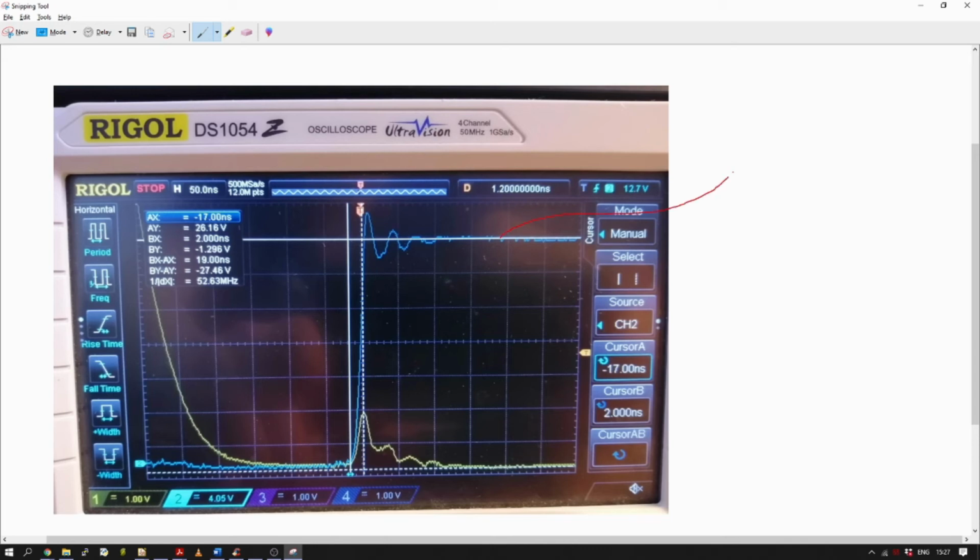So this here is the drain of the low side MOSFET, and as you can see, we're around 0 volts. Then there's a very sharp rise up to, there's some oscillation here. That's most likely due to my grounding. So when I took a picture, I'll probably flash up a picture of the setup here. Maybe I'll put it down here so you guys can see.